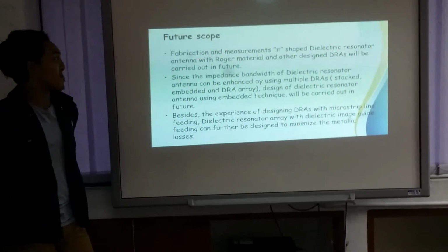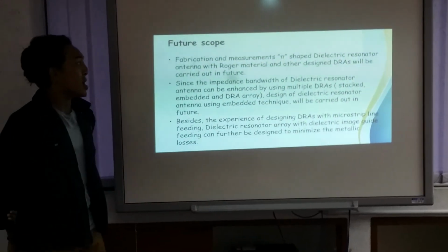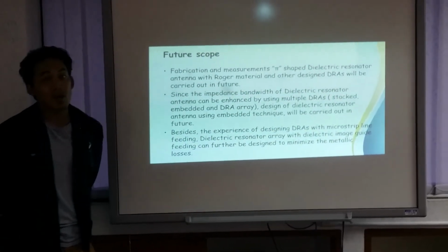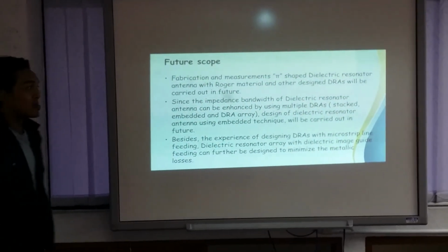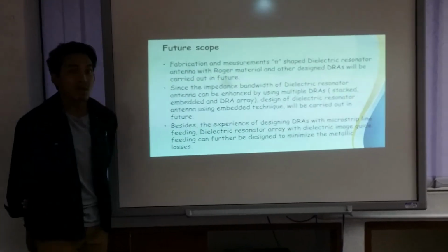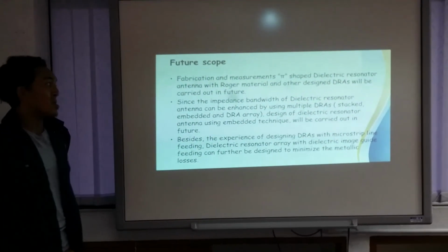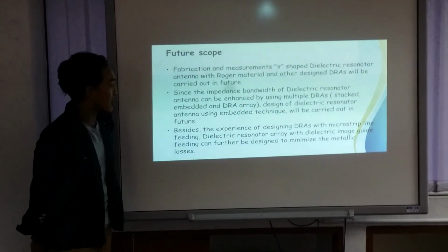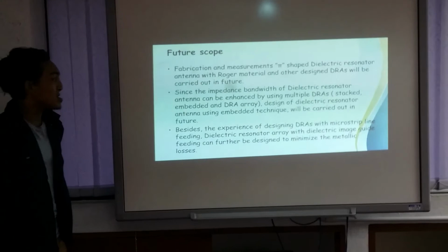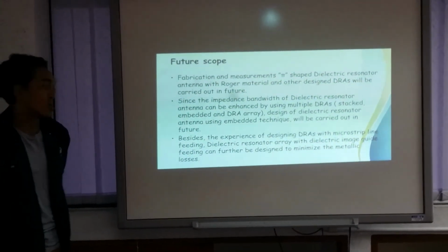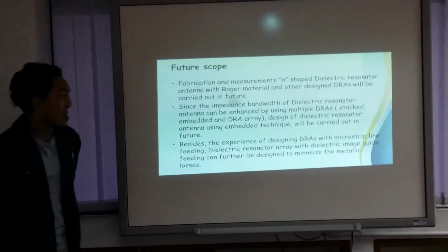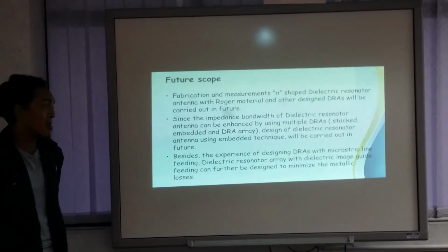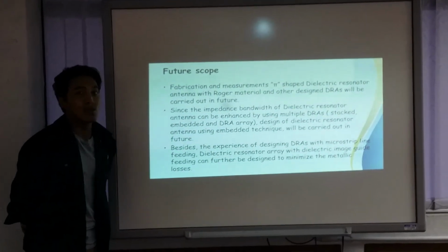Okay, for future scope, the first point is fabrication and measurement. Pipe-shaped DRA with Rogers material and other DRA designs will be carried out in the future. Next, since the impedance bandwidth of a DRA antenna can be enhanced by using multiple DRAs, design of a dielectric resonator antenna using the embed technique will be carried out in future. And besides the experience of designing DRA with microstrip line feeding, a dielectric resonator array with dielectric image guide feeding can further be designed to minimize the metallic losses.